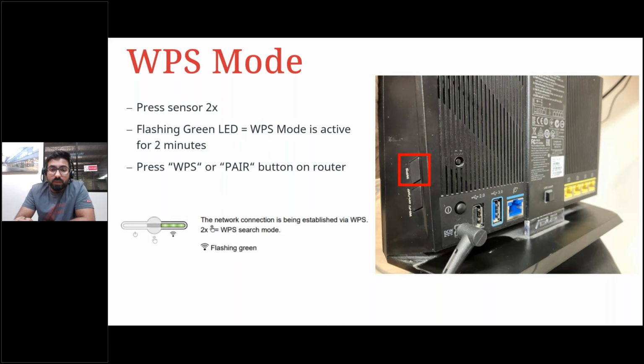It may take up to 2 to 3 minutes, and when the light goes solid blue on the right-hand side, that means the connection has been established. For those who don't know, WPS means Wi-Fi Protected Setup, or in other words, it's pairing without any intervention with the inverter.